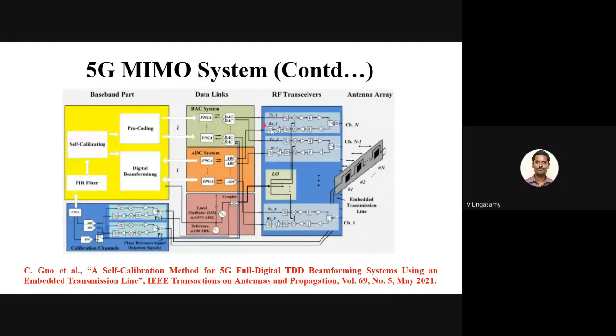Okay, we have to filter out or download the signal, then amplify that, and then give it to this one. So why do we require that? For example, if you go through the 3GPP spec, for small cell it is 24 dBm, which is a 250 milliwatt radio, and for micro cell it is, I think, 34 dBm, and for macro cell it is 46 dBm, I think. So beyond 46 dBm it will be a macro cell.